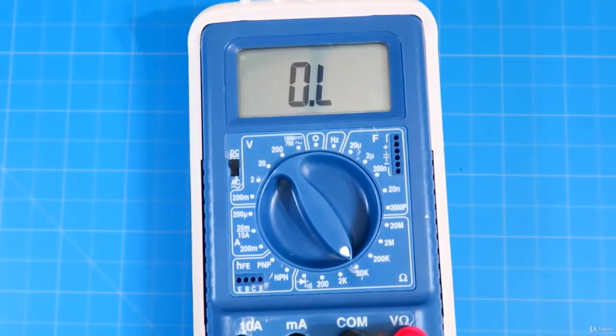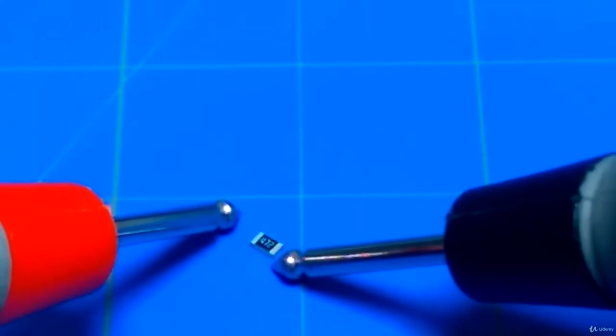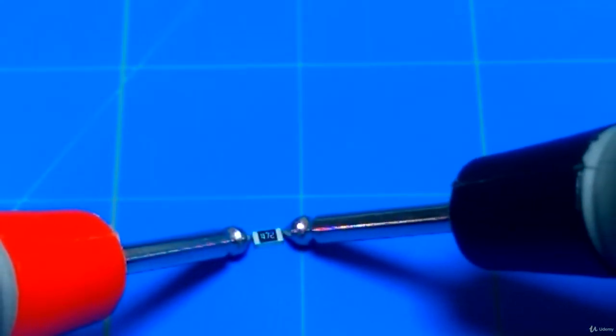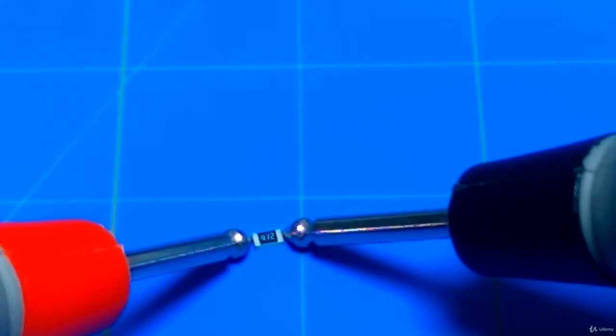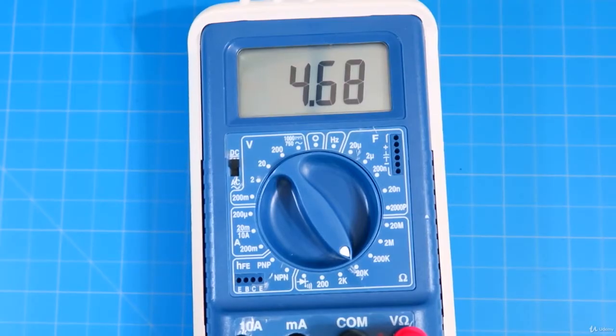All right. Okay, so let's try and put these probes up here, and let's see if we get 4.7K. All right, so it says 4.7K. It looks like 4.7K, so let's see what we got. So we put it up there, and ever so gently, and then watch the meter, and 4.68, yep. And this is probably a 5% resistor, so it's within tolerance. And again, there you go. Very nice. And that's how you do it. So if the number's on there, great. Okay, so you can read that.